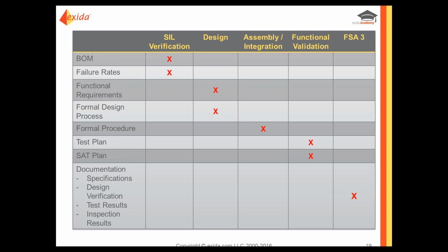But often, going along the same road, I've seen proof test coverage above 70% or 75% where people aren't requiring a leak test, and that's probably an indication it's invalid. We can help you with that, and maybe take it offline to look at specific applications. But there is guidance in the standard on what you can claim, and there should be traceability and a reasonableness test.